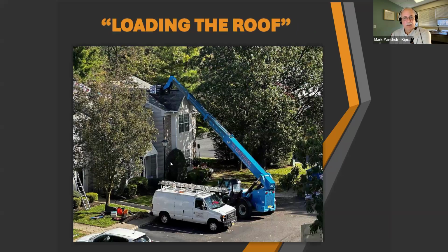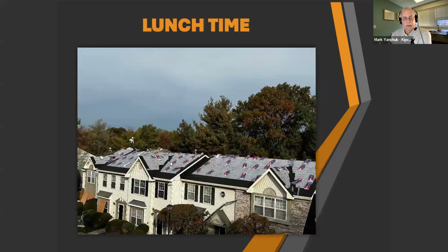This is some of the equipment that may be used. So most projects, most days start out, they tear off the roof in the morning, they strip everything, they start putting all the underlayments down, the flashings, replace the sheathing. Then by lunchtime, the roof is ready for shingles. They'll load the roof with the shingles, and then they'll break for lunch. And then when they come back from lunch, they're shingling.